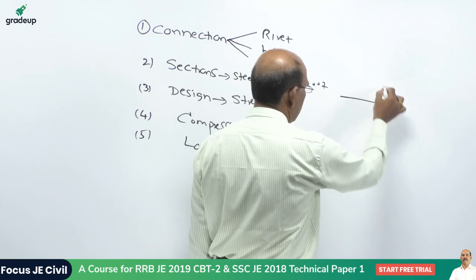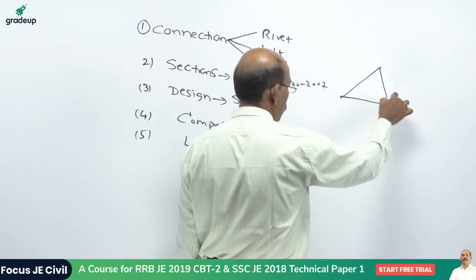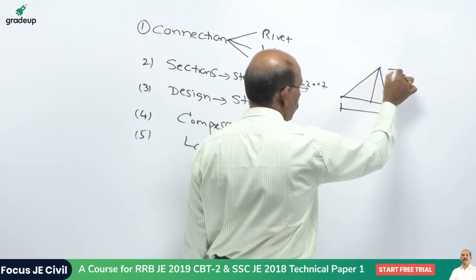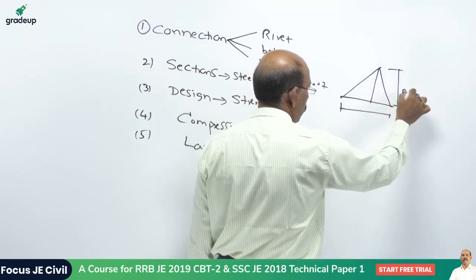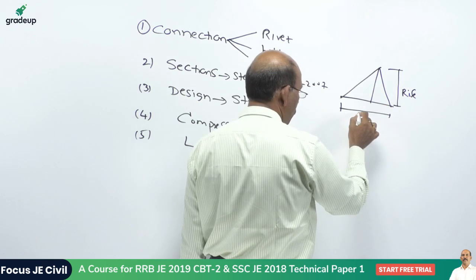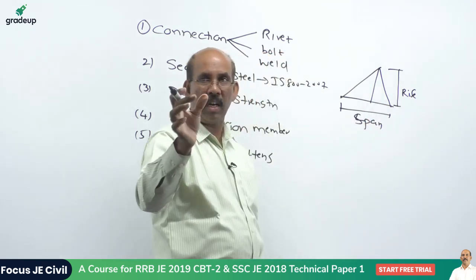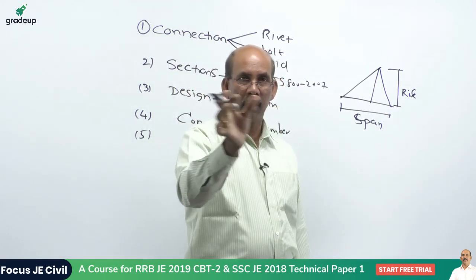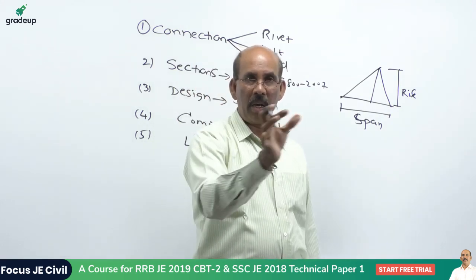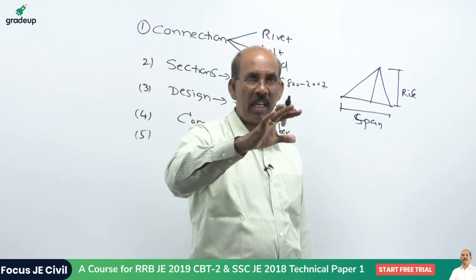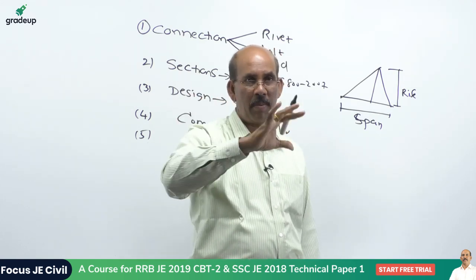In a general question it is given the rise and span. So we are going to calculate the rise and span, and accordingly the pitch and the slope, and accordingly you select the type of the truss.